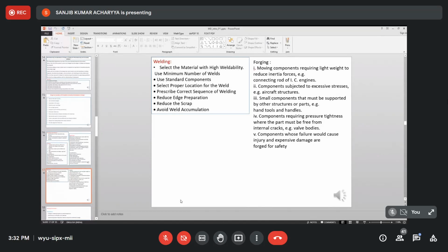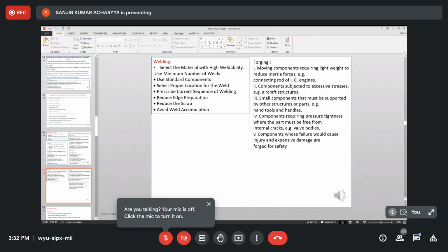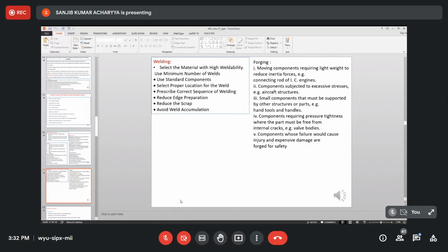So what are the related questions? What material is suitable? What are the effects of the manufacturing process over the component? During the machining process, the material property can be changed to a certain extent. Residual stress may be there. The designer has to know whether he can allow the residual stress in the component due to machining or not. If possible, machining will be accepted. If not, machining should not be accepted. An alternative manufacturing procedure is to be sought out by the designer.